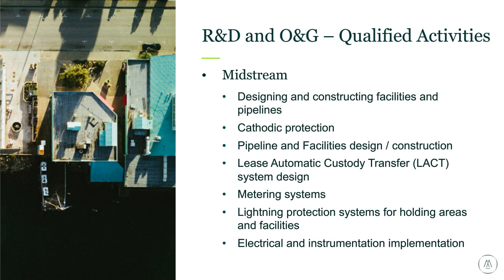You have cathodic protection and other corrosion control systems. Oftentimes, pipelines need to have pretty much a lightning rod on the pipeline, so lightning doesn't strike and corrode the pipeline. Corroding pipelines have to be shut down. They can be damaged. They can have explosions. Just a lot of dollars lost from a shutdown or a catastrophe standpoint. So there's a lot of protection and thought that goes into pipeline construction, the actual pipeline design and facilities design construction.